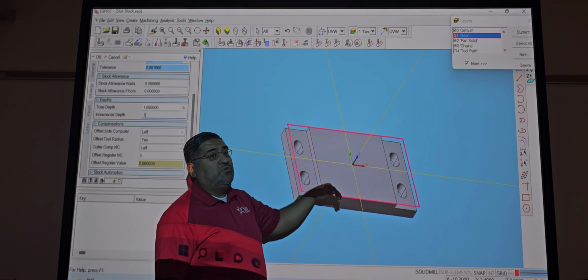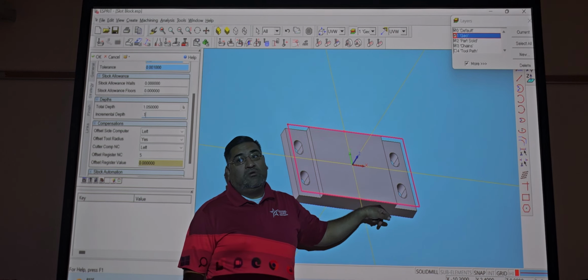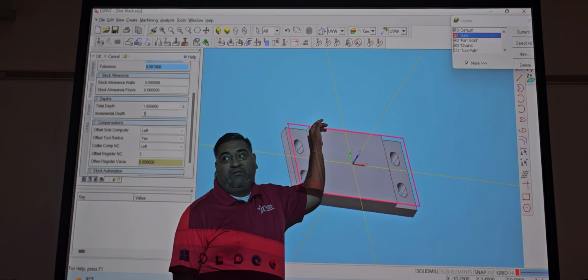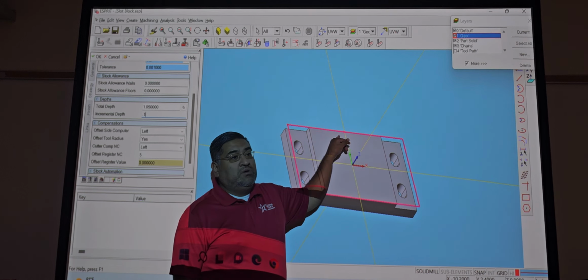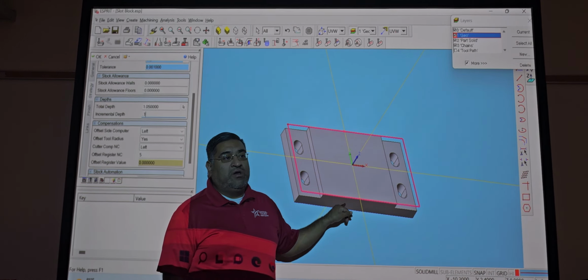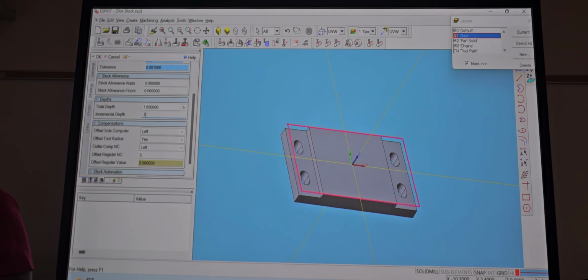If I put the opposite way, my end mill is gonna be taking off that material, and the part's no longer gonna be 4.5, it's gonna be 4 inches, because it's gonna take a quarter here and a quarter there, right? That it'll take off. It's just the radius of the diameter of the tool.